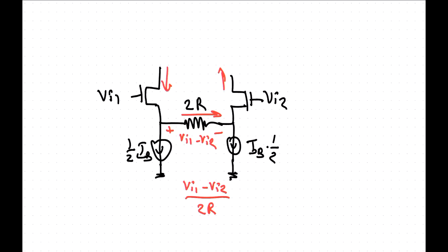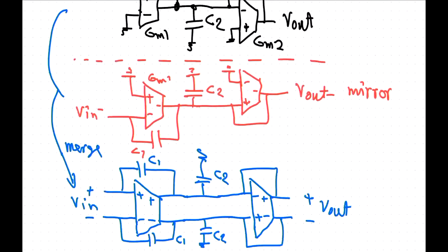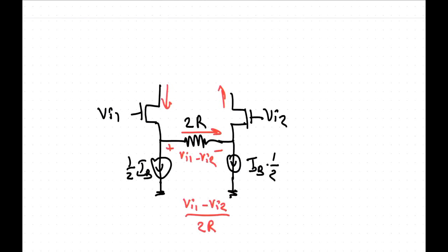And then, if you want to make a single-ended transconductor, we want to subtract those two currents. Now we could subtract those two currents by putting a current mirror up here. It is more common to put that structure into something that looks like a current mirror op amp, because if we put just a current mirror up here, then the voltage restriction on that node is that this has got to be in saturation, so this can't swing too low, and that's normally too restrictive.